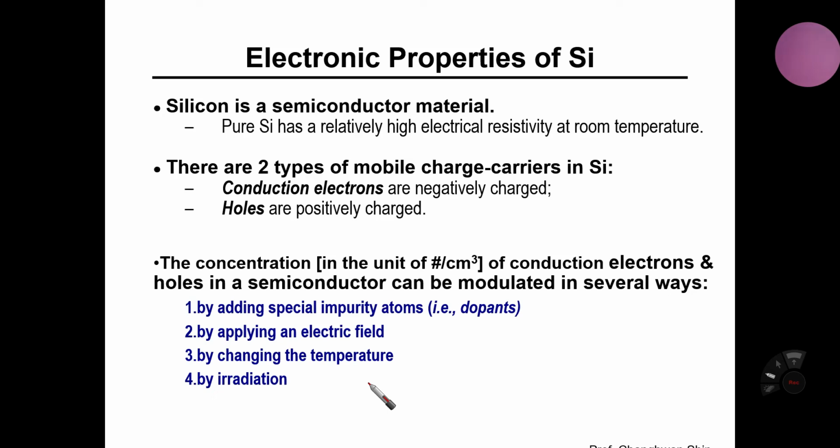That is hole. Electron is the thing that really exists within a silicon material, but hole means an empty one, a vacant one. So a hole is not a really existing particle. However, a hole itself looks like a particle which is moving around within a silicon diamond structure, the silicon crystalline material.